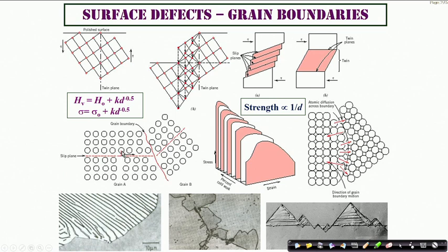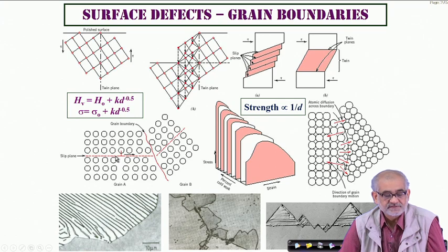So the point is, if I have such boundaries present, then a dislocation, which we just heard is the main agency required for explaining or defining any kind of deformation of crystals, can find its way all the way up to the boundary, but then will face a barrier across the boundary because the continuity changes here, or in other words, the orientation changes. So the stress which was responsible for moving the dislocation up to the boundary will no longer be able to move this particular dislocation into the other domain. It is as if this is a boundary between 2 countries, and you have a border here, so obviously this fellow cannot move to the next country without disrupting.